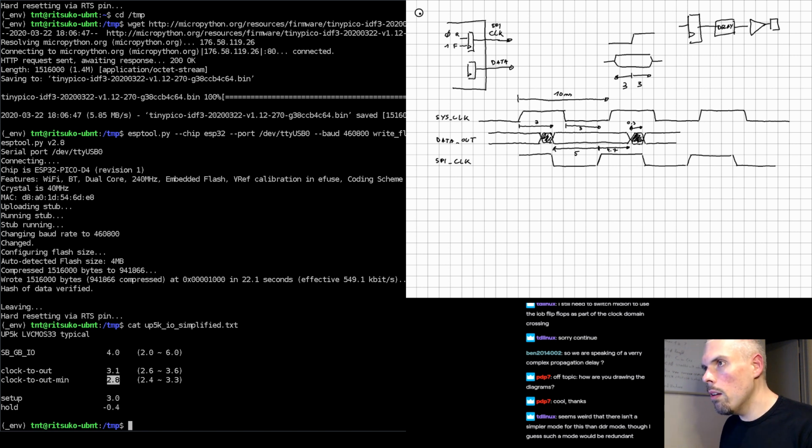And right in the middle, you have a programmable output delay, which you can set from like 0 to maybe 2 nanoseconds, which allows you to shift your edge by whatever value you want. It's not especially calibrated, but it's used, for instance, in RGMII, the gigabit interface. That's something you could use. The ECP5 has that.